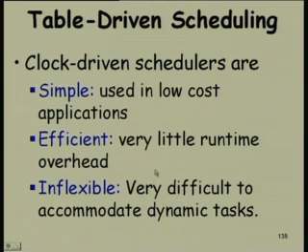This is a very simple scheduler, nothing much for the scheduler to do except consulting the table, and as soon as the table ends, start from 0. Very efficient, very little runtime overhead, it can have just a few instructions.